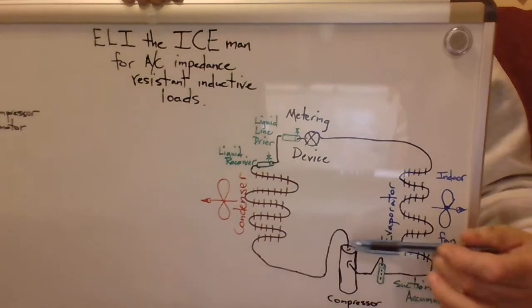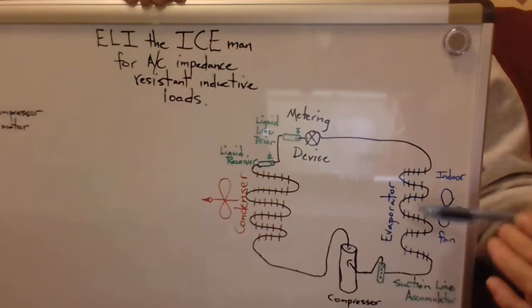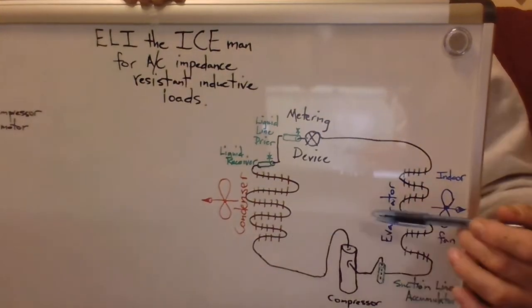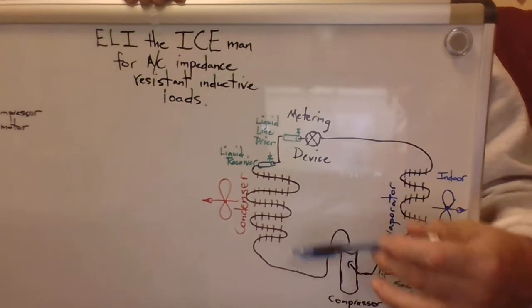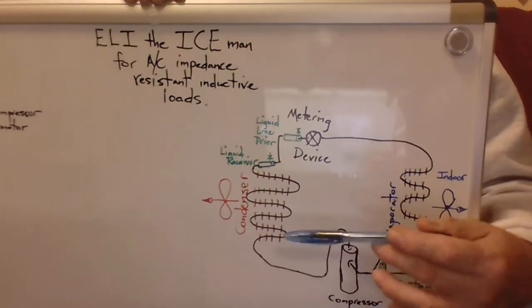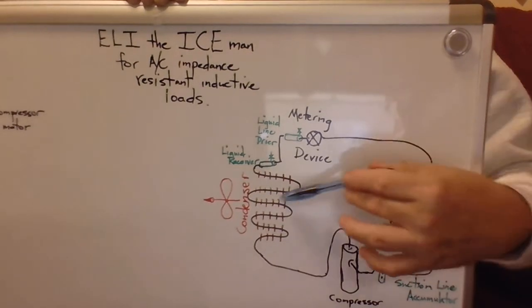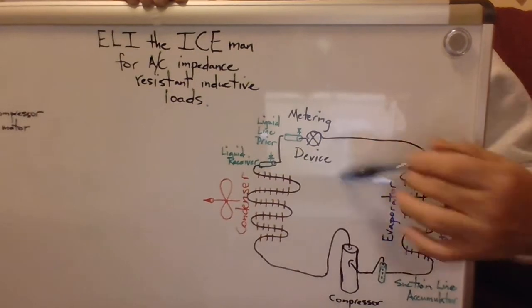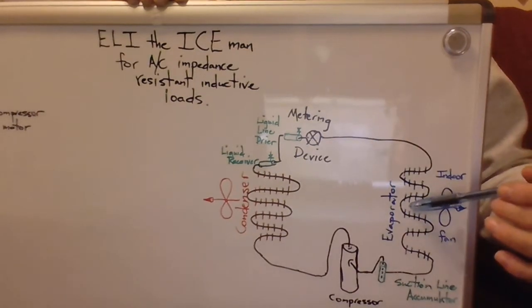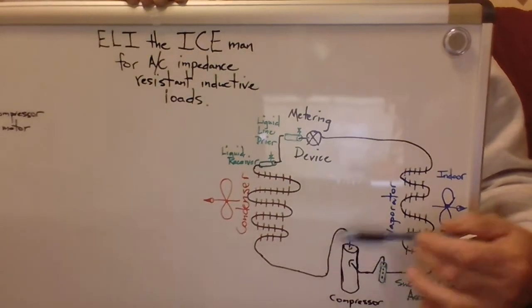Very simple concept. When it comes to heat pump, you really need to speak in terms of outdoor and indoor, because this switches back and forth with the reversing valve. But that's a discussion for a later date. So once again, the basic elements are very, very important here, because if your subcooling is way, way high and your superheat's way, way high, one of the first things you need to begin to think about is what's causing